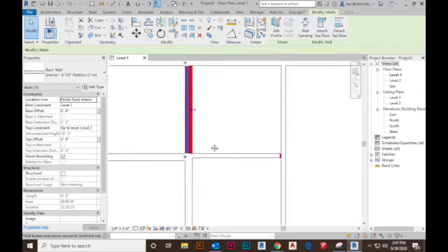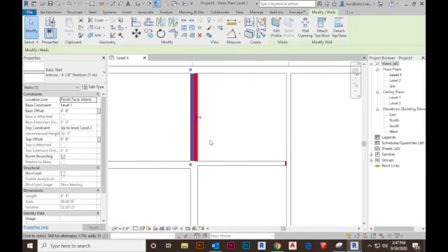If we highlight that Revit interior partition, we can see below, through the little bit of transparency that it gives us, we're aligned correctly on the west wall, but the wall underlay seems to be thicker. That means we've got the incorrect wall type on top of that drawing.